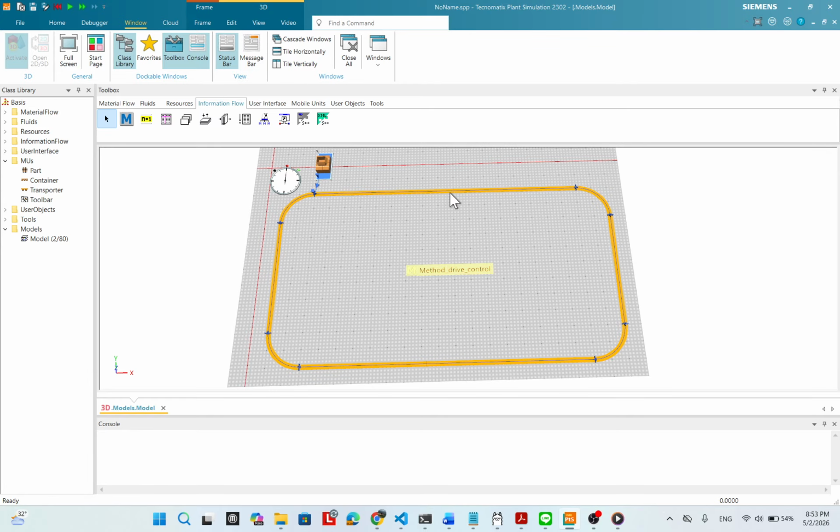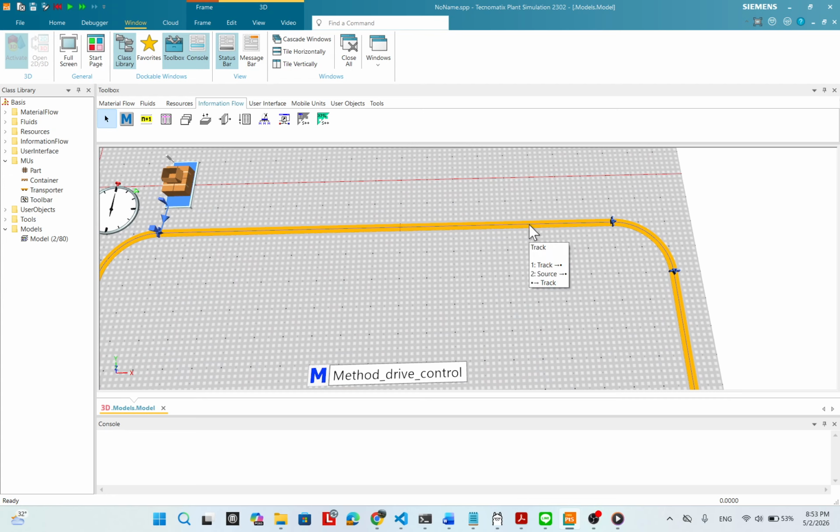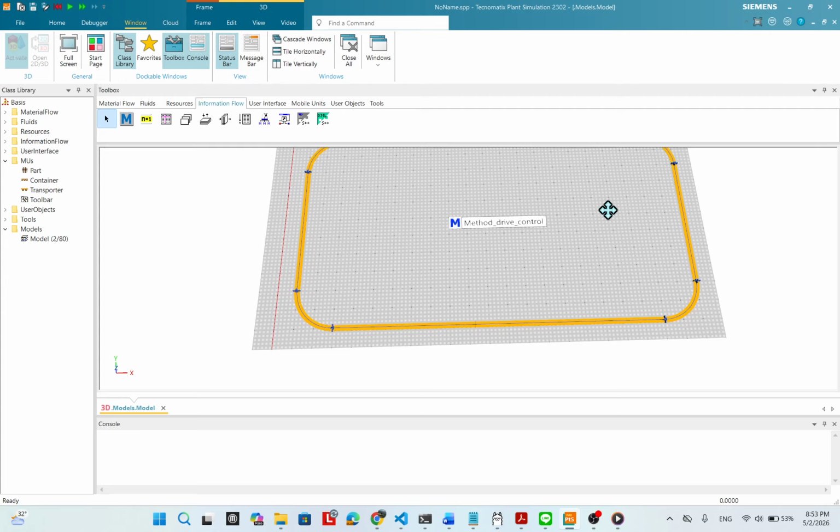The behavior of the AGV is going to be moving along the track, and this sensor tells the AGV to stop over here and start to roll the material onto the AGV car, waiting maybe 5 minutes, and let the AGV go to the next sensor until the AGV stops and touches sensor number two, and starts to unload the material, unload the object on the top of the AGV, to maybe a buffer, which receives it and continues the process to the next station.